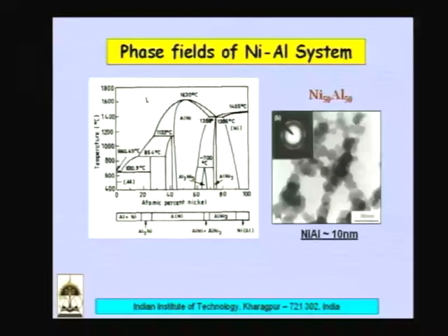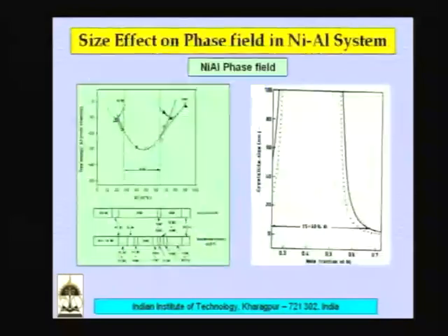Once the segregation has occurred, it becomes very difficult to produce a particular composition, and ultimately you may not end up in a single phase, but in a two phase mixture, and if your goal is to make a single phase, you have a problem. So as a result, nanocrystalline materials have an advantage. One can have a wider range of composition and still have such a compound formation.